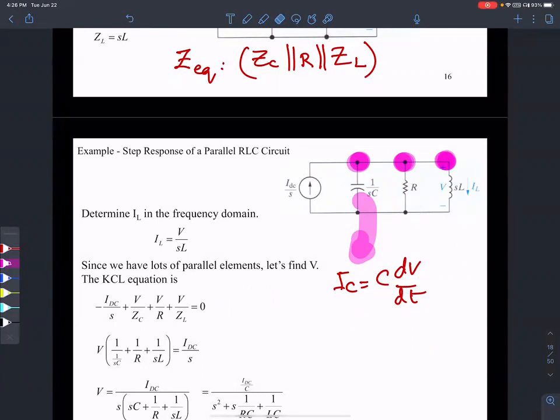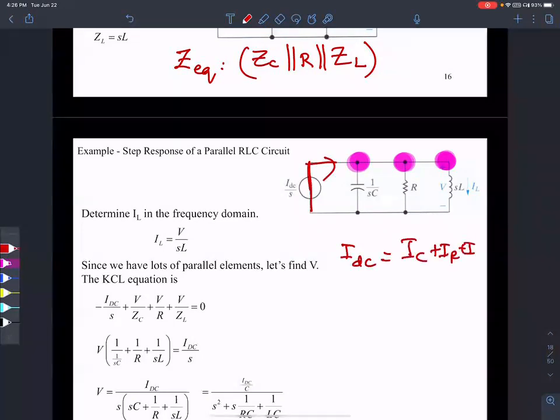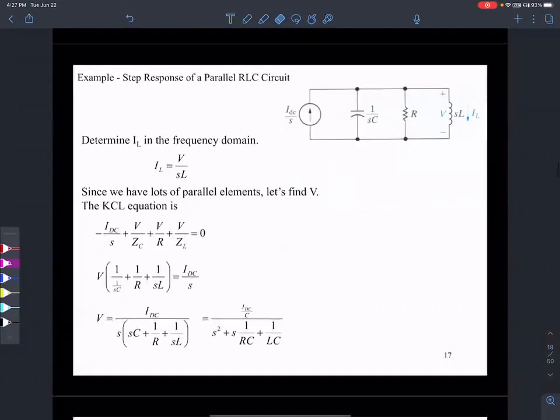So what we did was to set up equations for current, and then this current was summing up to the current in the capacitance, current in the resistance, plus current in the inductance. That's exactly what we are doing here, except that we are bypassing the integral differential equations. We are simply writing the equations in the S domain form.